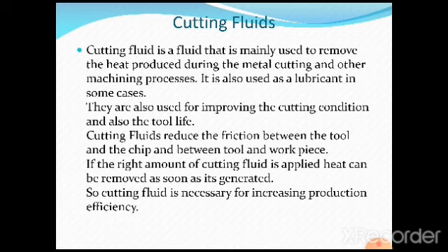It is also used as a lubricant in some cases, because a lubricant can give the correct amount of cooling action at the cutting tool and chip interface. They are also used for improving the cutting condition and also the tool life, as we have discussed. The more heat generated at the tool chip interface, the more the chances of the cutting tool losing its cutting ability in the machining process.